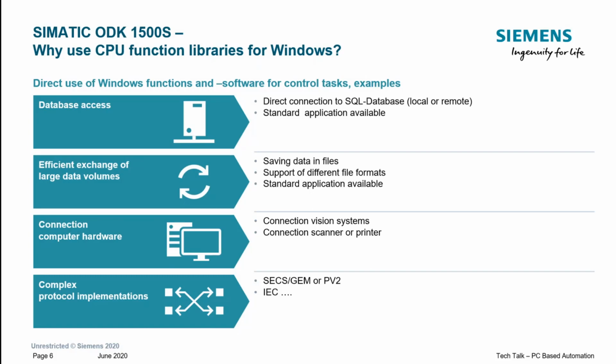Now we did look at using the T-send and T-receive blocks inside the PLC, but as we're all familiar, a PLC is just not designed for string manipulation. It's not what they're designed to do. So it becomes very complicated if you're sitting and writing SCL to handle T-send and T-receive. So these open controllers and these software controllers really do shine when it comes to connecting to weird and wonderful bespoke protocols that have been derived.